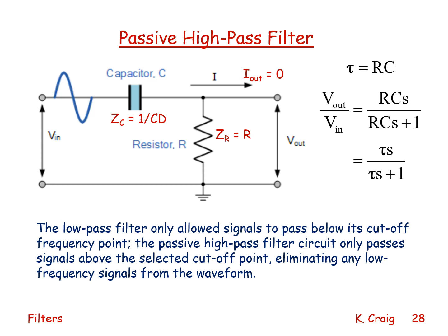What is a passive high pass filter? Well, we simply interchange the capacitor with the resistor, and we measure the voltage out across the resistor, and we get what we call a high pass filter that's passive. The capacitor has an impedance 1 over CS.